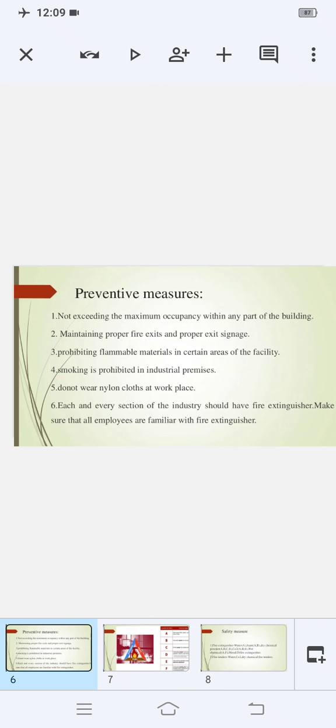There must be fire alarm equipment. These systems are placed in conspicuous locations in all parts of the plant for promptly notifying the fire brigade and for exit of the employees. This system operates on an electrically supervised circuit, and these systems are mounted so that accidental operations are not caused by vibration when they are installed inside the building. Fire alarm systems can warn of the presence of smoke, radiation, elevated temperature and increased light intensity. Each and everything must be under control.